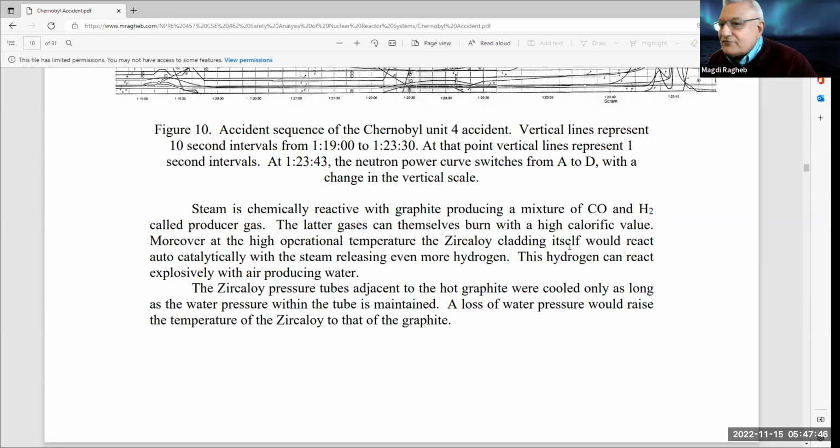You have the CO plus H2, you have the H2 from the interaction of the steam with the cladding, and that interaction of steam with the cladding happened also in the Fukushima accident on a big scale because those boiling water reactors had a core that would spray water if the core is uncovered. It is not mentioned in the open literature, but that's a flaw in existing boiling water reactors. If you have a very high temperature, you can use core spray, as it's called, but only at low temperature. At high temperature, you get that reaction where hydrogen is produced and released to the containment. And in fact, it seems that that's what they had in three of the 4 reactors at Fukushima. They had hydrogen being released. They couldn't diffuse it out of the containment, and then it is documented that we had hydrogen explosions in that case.